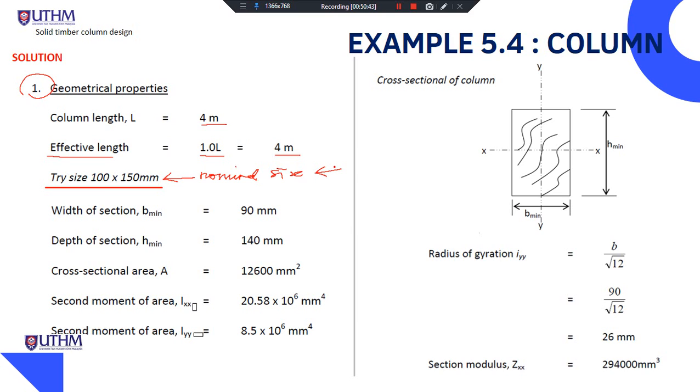This is the case for dry timber, so you need to refer to table B3B for sawn timber at dry condition, or table B4 for dressed sawn timber.